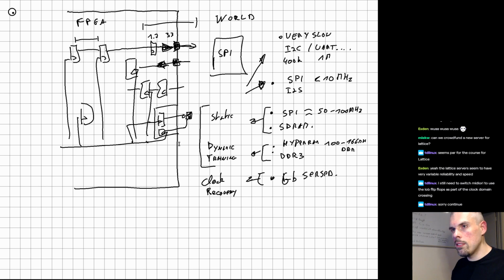But that's a huge net that needs to be distributed everywhere in the FPGA, and having a certain physical size, the clock edge doesn't happen absolutely everywhere at the exact same instant. The various flip-flops are also not entirely triggered at the same time, depending if it's a rising edge or a falling edge.